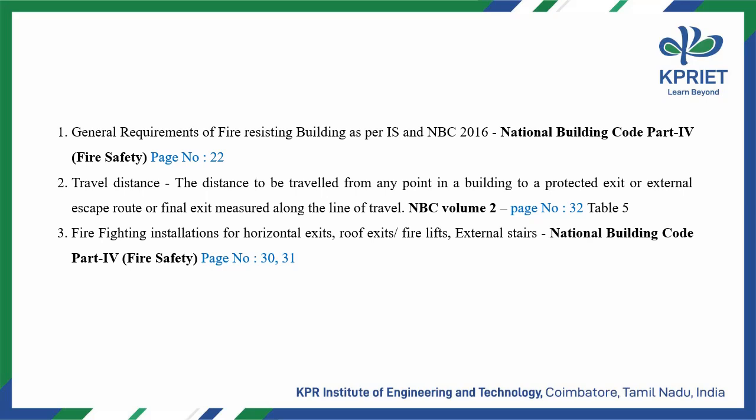Code books to refer. General requirements of fire-resisting building as per IS NBC 2016, National Building Code Part 4, Fire Safety, page No. 22. Travel distance, the distance to be traveled from any point in a building to a protected exit or external escape route or final exit, measured along the line of travel. NBC Volume 2, page No. 32, Table 5.